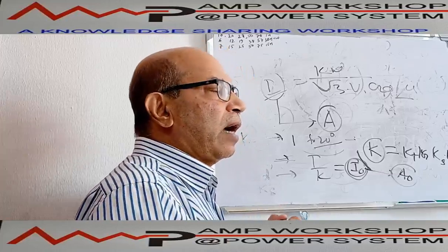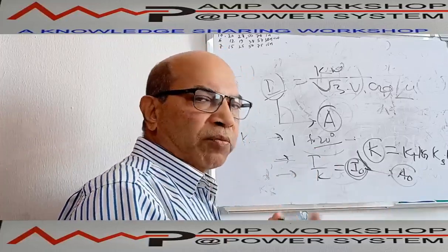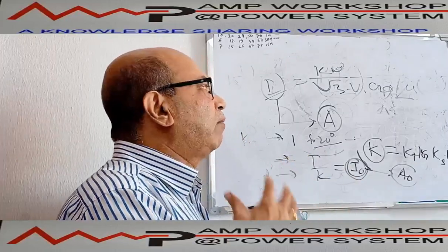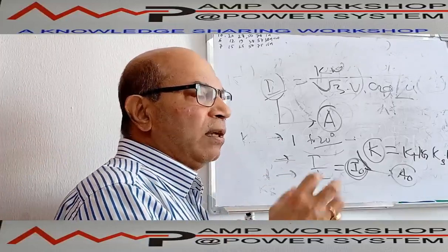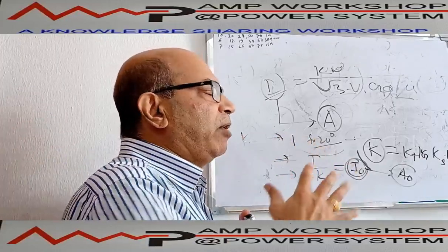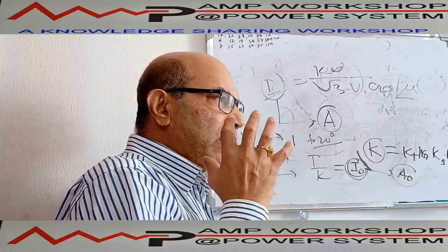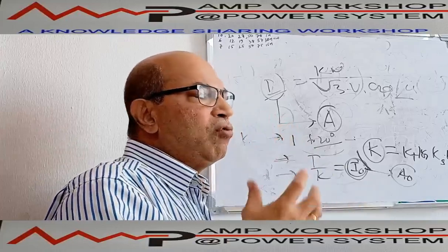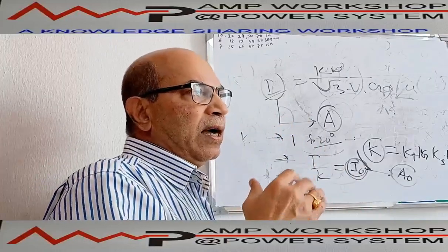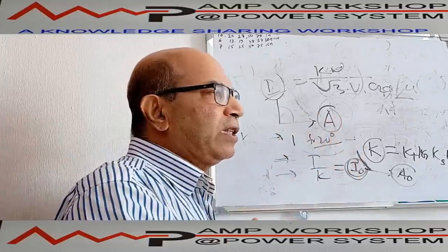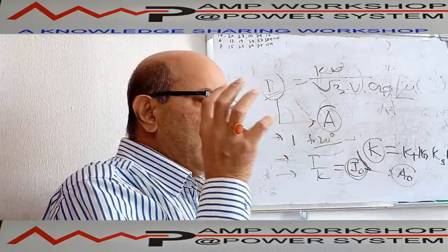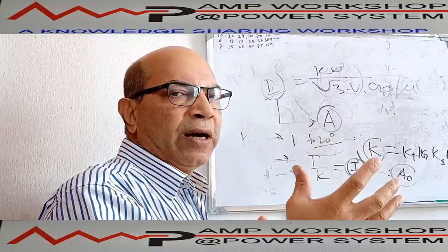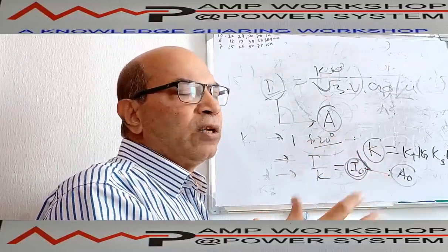But one thing I want to highlight: there is various software available to calculate the cable automatically, but you have to make sure they are using the right formula for voltage drop, not the simple formula, and that all the constants have been considered properly. If it is the design stage, then you use the IEC parameters. But if it is after procurement of the cable, for the final check, you should use the respective manufacturer catalog, not the IEC, because the manufacturer design may be different at the temperature, and all the factors may be different.